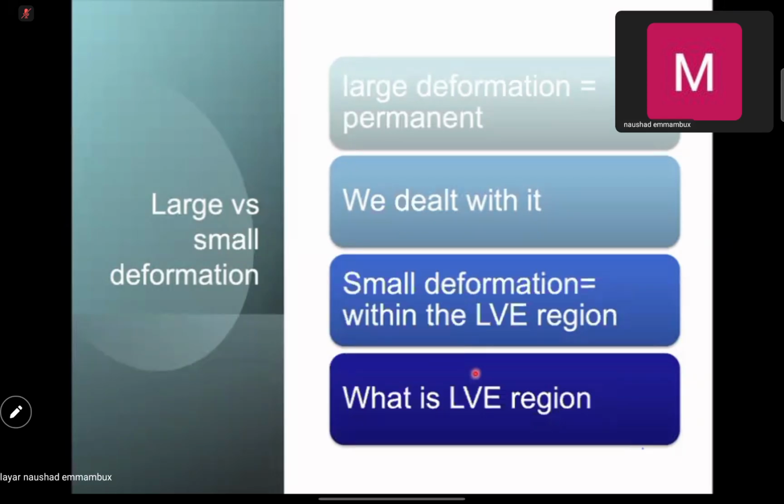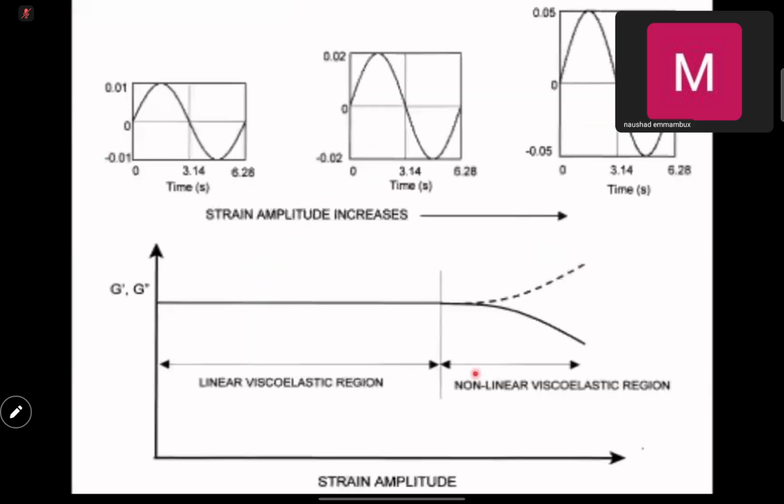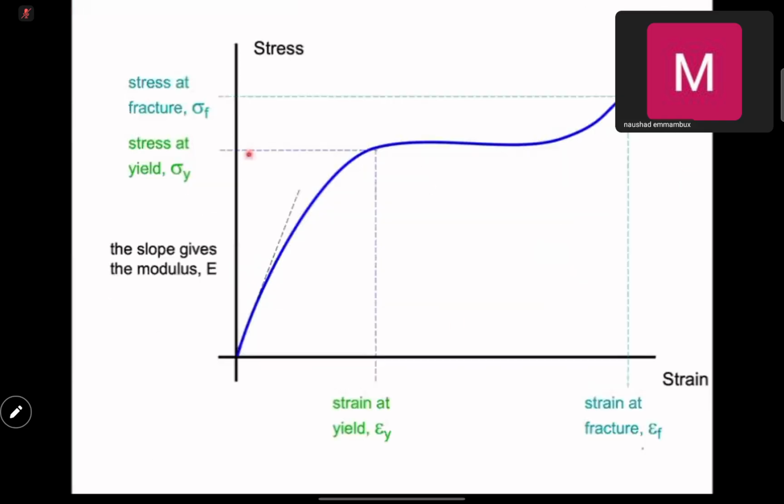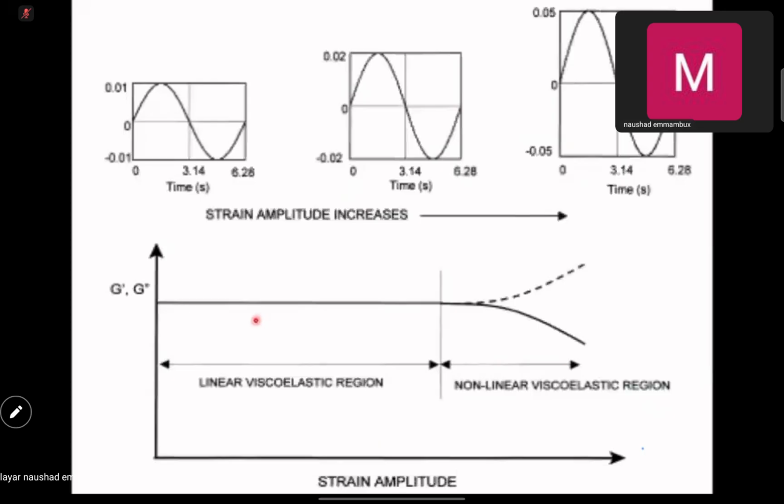So whatever rheological parameters you are measuring, first you need to calculate the linear viscoelastic range. If you remember the stress strain curve, we talk about the linear viscoelastic range where the strain is linear with the stress, and then you get a constant modulus, here the Young modulus of elasticity, for example. So how do we calculate the linear viscoelastic range?